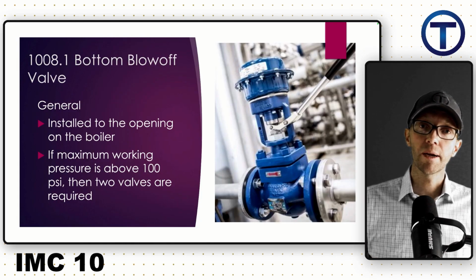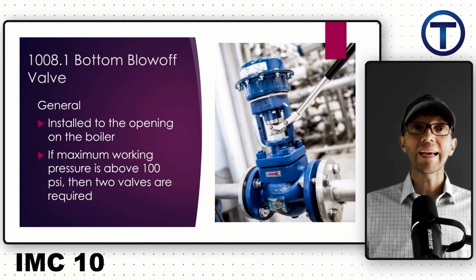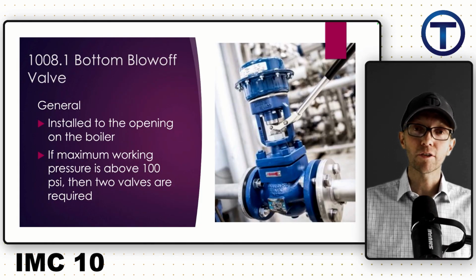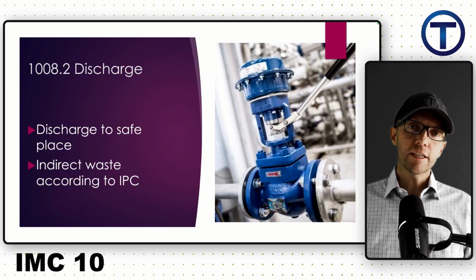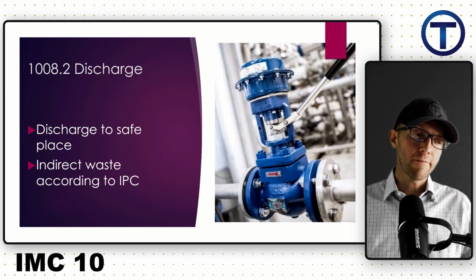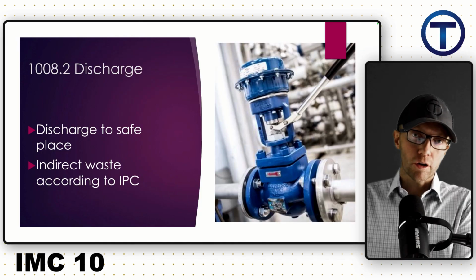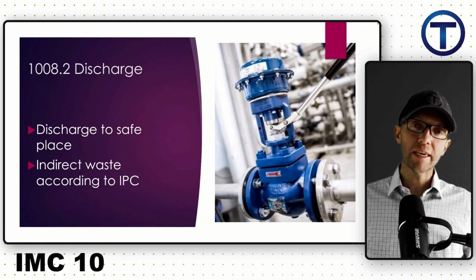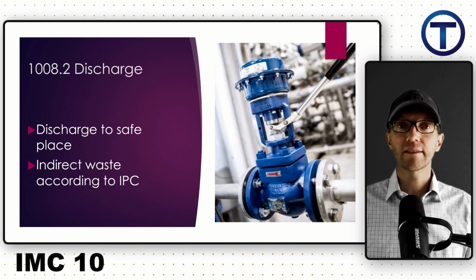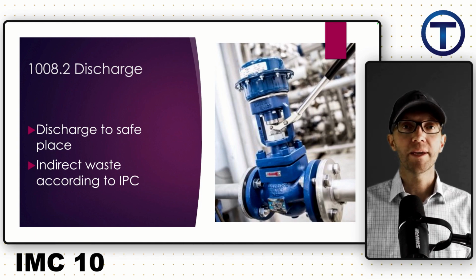Now, of course, all the piping involved would need to keep that safe because the last thing you'd want to do is be blasting someone else or yourself with superheated sediment. That said, the discharge for a bottom blow-off valve needs to be discharged to a safe place. And of course, we're going to play by the rules of International Plumbing Code, do some indirect waste, air gap, and then we'll be in good shape.